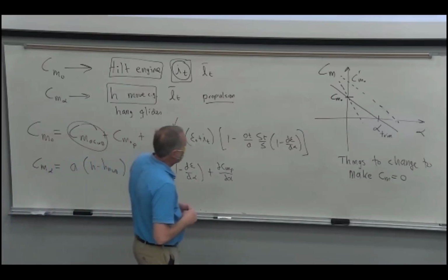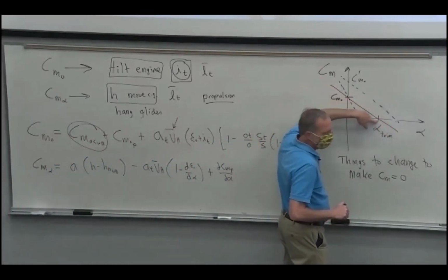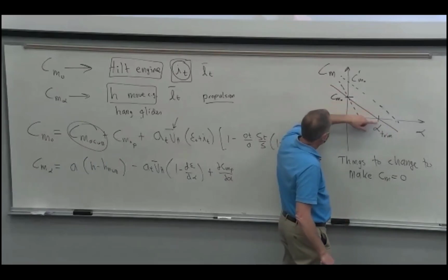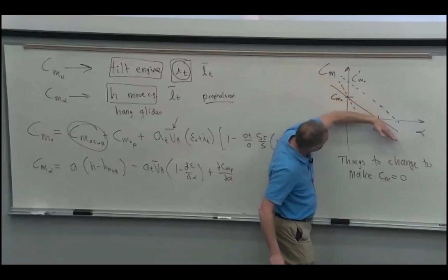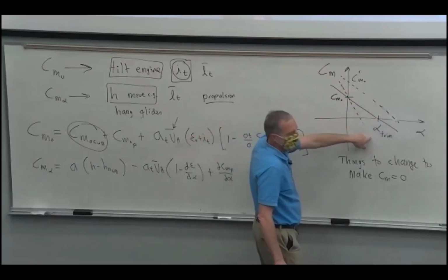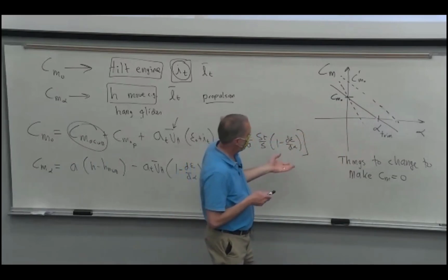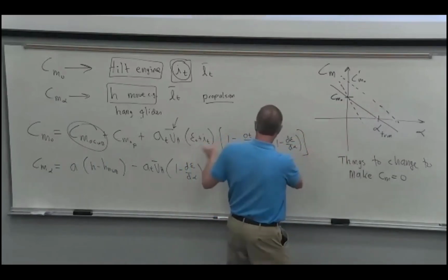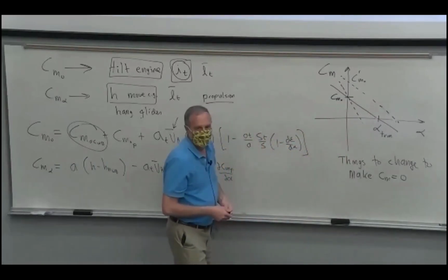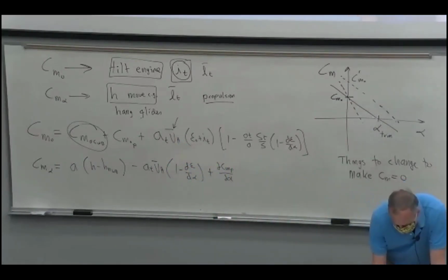So we've said, okay, well, if we have a certain curve here and we have an alpha trim we want to trim at, then we need to make sure our curve goes through that at 0, so that we get pitching moment of 0 at alpha trim. But what alpha do we fly at? Because here we're saying, okay, well, at the right alpha, we need to make CM 0. So I just want to remind us real quick of what the answer to that question is.